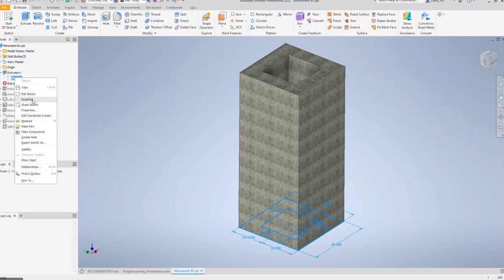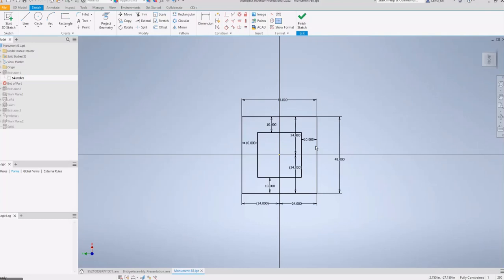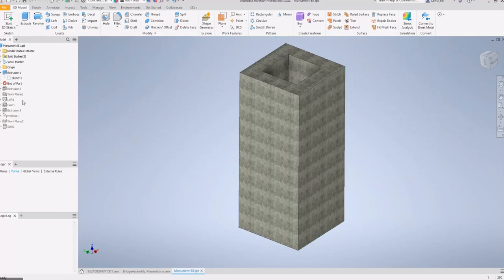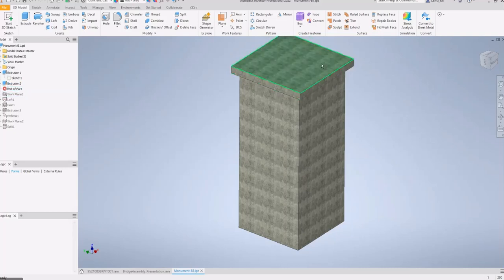You'll notice all this actually does just start out with a sketch. And a lot of our folks all of a sudden can see this and say, okay, I can do that. Then it's not much of a difference to just click extrude, and then you can extrude that sketch up a certain amount until you get that feature that you're looking for. I'm going to roll this part down a little bit more. You can see that in the same fashion, we added a cap to that. There's a little loft for an architectural top on that. And of course, I'll jump down to the bottom.